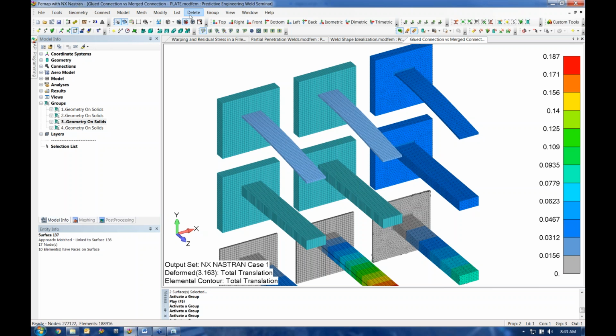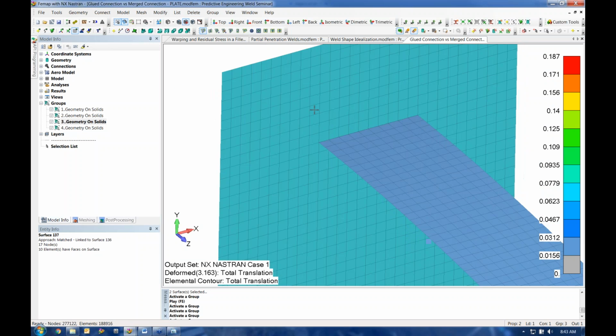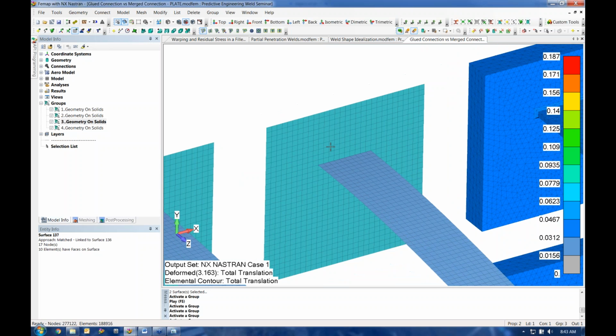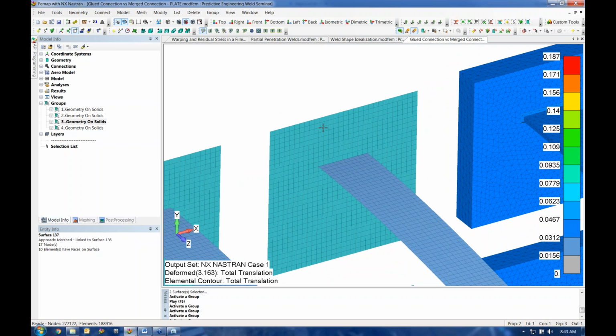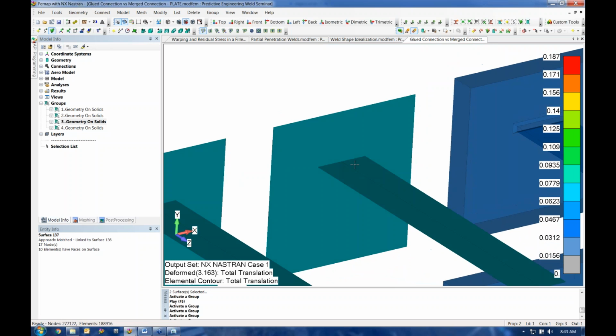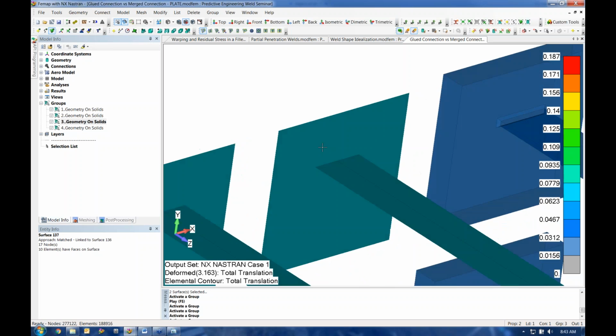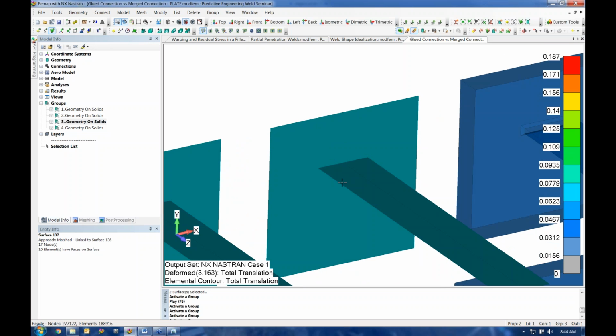And then as we move on to the left here, if I turn on thickness, it'll be a bit more apparent that this next one over, we've merged the nodes. So for our geometry, we've created one continuous sheet solid. The nodes merge along that edge, and we don't really have to worry about the connection. If we do the setup in the geometry correctly, we're automatically going to be connecting these different parts. So what we have here, this is a sheet solid, one continuous solid made up of multiple surfaces. So even though we don't have any actual thickness to this part, we still call it a solid because it's all one part.